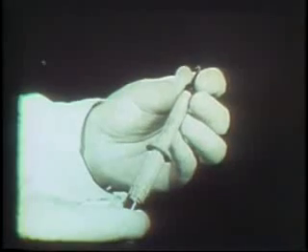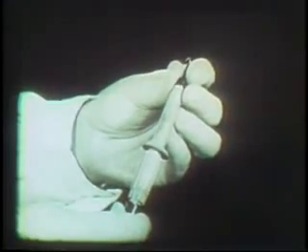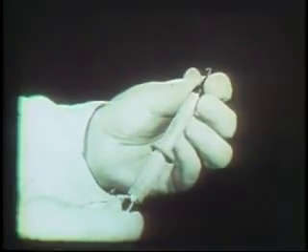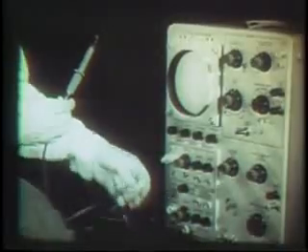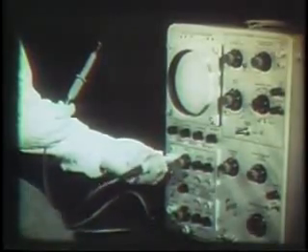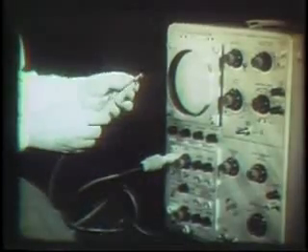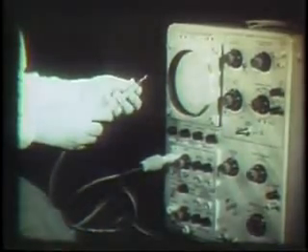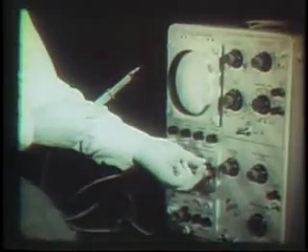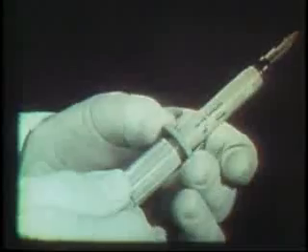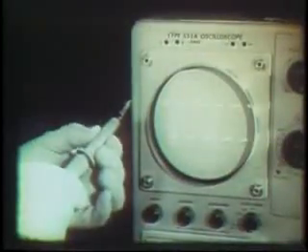How do we properly adjust this capacitance? It is really quite simple. Again, the square wave comes to our aid. Since the square wave contains a wide range of frequencies in a single waveform, the voltage divider can easily be compensated using this one signal. We feed the signal from the calibrator into the probe and then to the scope. By adjusting CP in the probe, we can see the effect it has on the square wave.